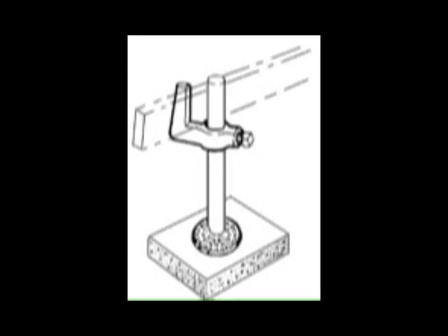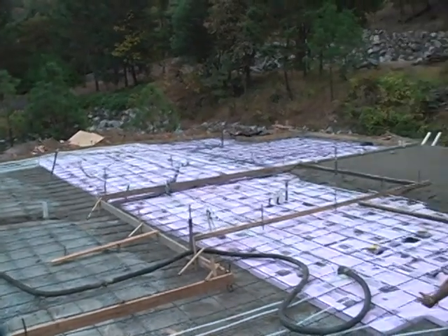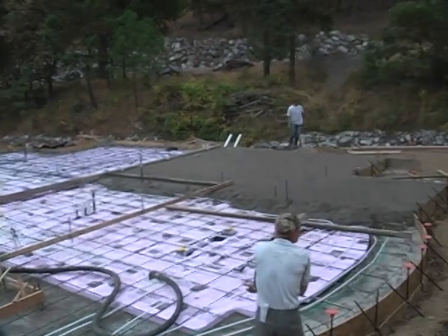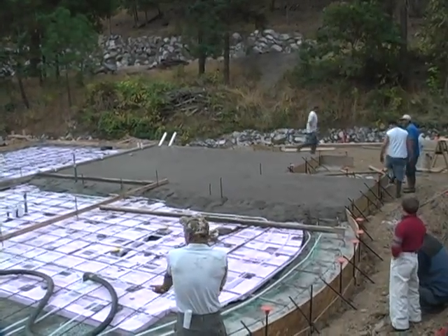This way you can then pull the screed board off, pull the screed hook and the screed post all out of the concrete, and then set up another section to do once you've completed each section. It allows you to move with smaller areas at a time and not try to move so much concrete and flatten it out at once. So this is a perfect example of that. You can see we've got this set up into a number of different shutoffs where we can pour just a little bit at a time.